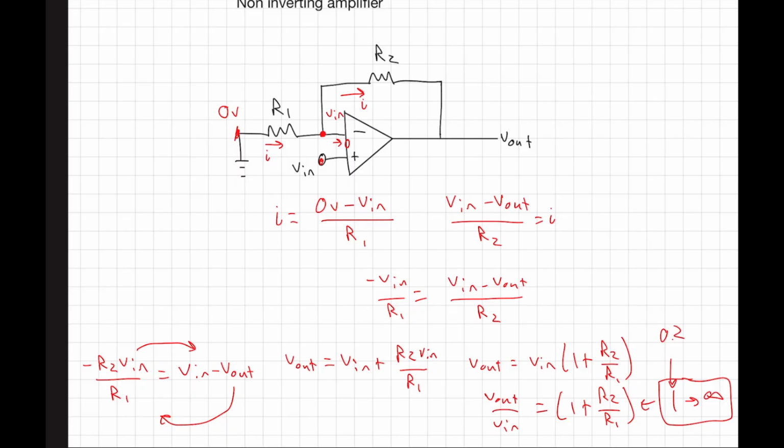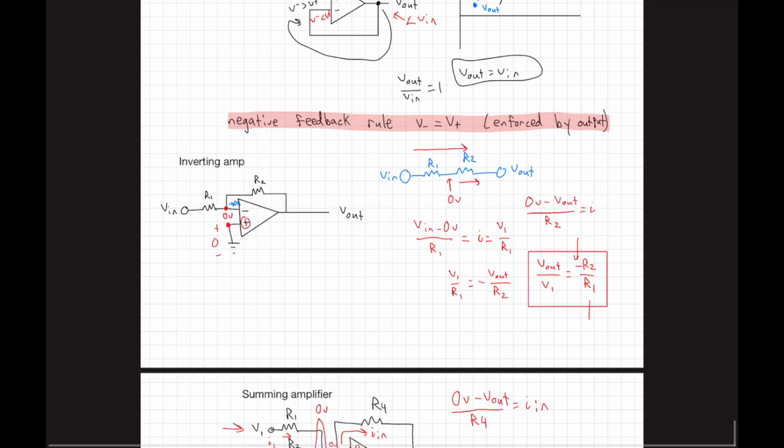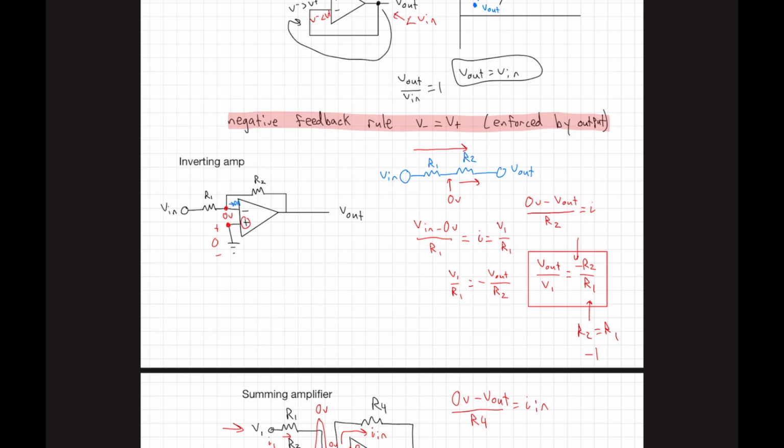So what we can do usually is cascade two inverting amplifiers. So recall that this has an output negative R2 over R1. So if you made R2 equal to R1, then you get a gain of -1. So you invert it. So if you follow this amplifier up with the same amplifier with R1 and R2 equal to each other, then you could get your output to be whatever this gain was, making it positive instead. So that's pretty good stuff.